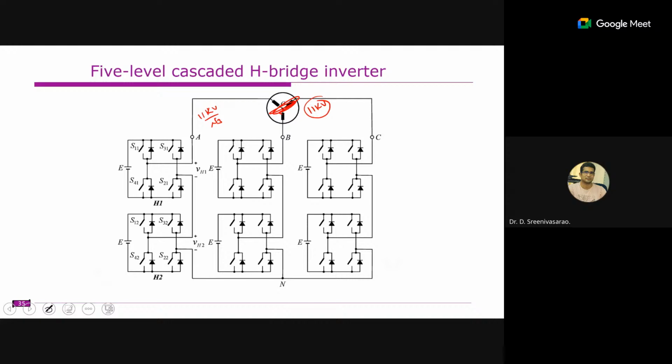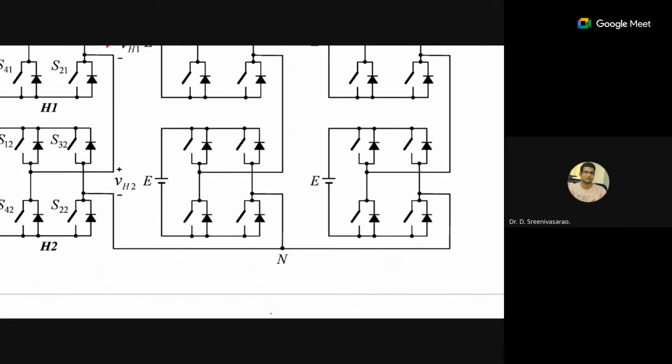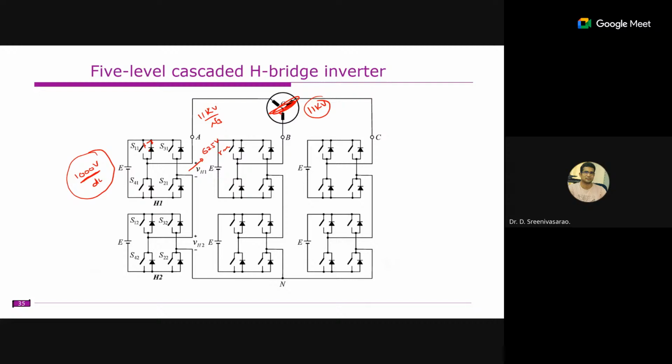Usually, if you have 1000 volts on the DC side, there is some proven rule of thumb: you normally get 625 volts RMS on the AC side. So if you are selecting 1000 volts, each switch, maybe you can use a 1.7 kV switching device if you consider some factor of safety as 1.7 or so. So accordingly you can adjust.